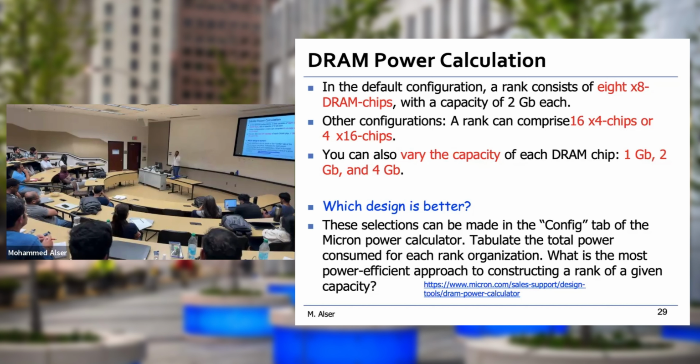Assuming you maintain the parameters for activating a row, charging, discharging, and all these parameters. We discussed tREFI, which is the refresh interval. This is one of the parameters that you really need to meet when you build your own system for the memory device.